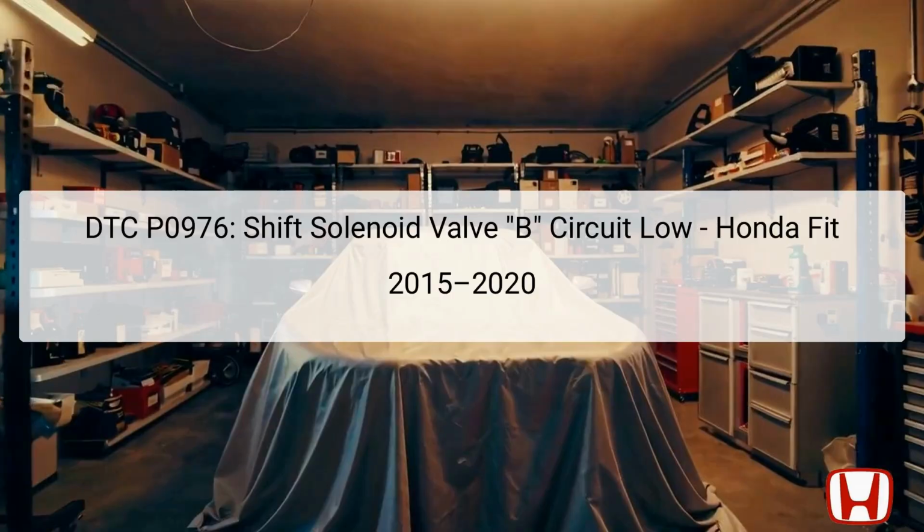The DTC P0976 indicates a problem with the shift solenoid valve B circuit, specifically a low circuit condition. This Diagnostic Trouble Code, DTC, is specific to continuously variable transmission, CVT systems, used in the Honda Fit from 2015 to 2020. Shift solenoids are responsible for controlling fluid flow within the transmission to manage gear shifts.